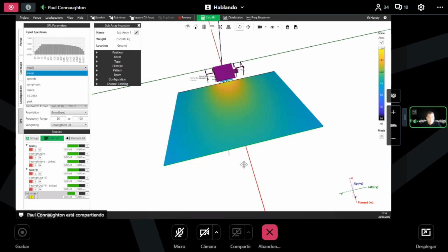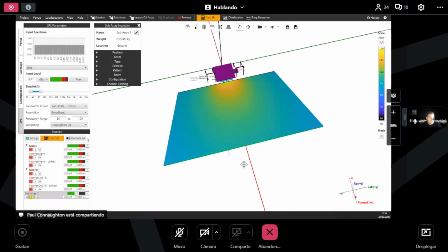Different input reference signals can be used depending on the type of sound source you want to measure or analyze. Today we're going to set our input source to pink. If you could all set your input source to pink, you can now watch all of your system meters go red, just to show you what happens here and why this happens.